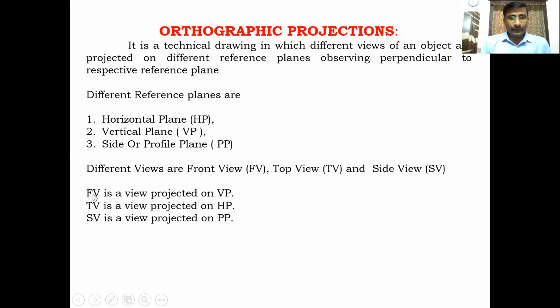The side view is always adjacent to the front view, on both sides of it. If it is a right side view, it goes on the left side of the front view. If it is a left side view, it goes on the right side of the front view. Clear? The side view is observed when looking at the object from the side, either the left side or the right side of the object.